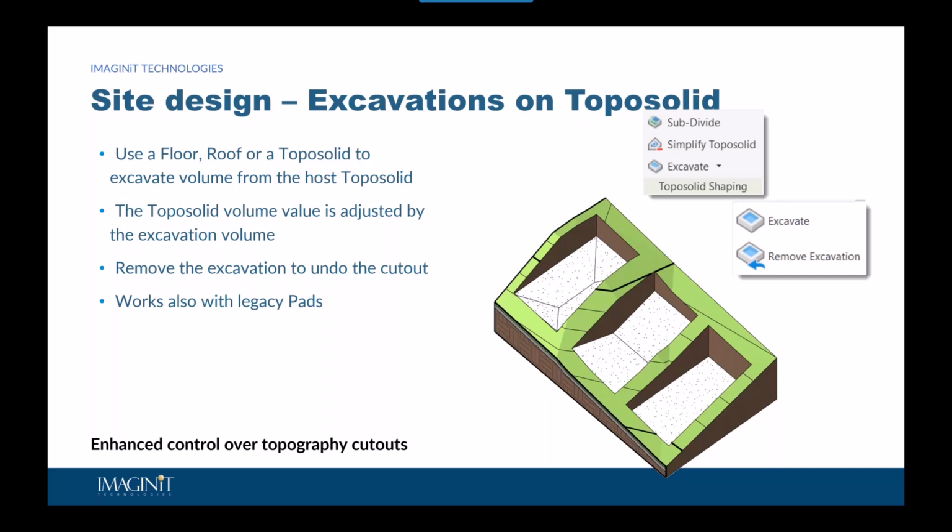There are cases where the excavate tool will fail due to any sharp triangulation facets existing near the cutter element, or the point is located on the edge of the cutter element. Users can adjust the topo point height to avoid those sharp edges, or adjust the cutter boundary. This is a known geometry limitation and technical difficulty with the Boolean operation.